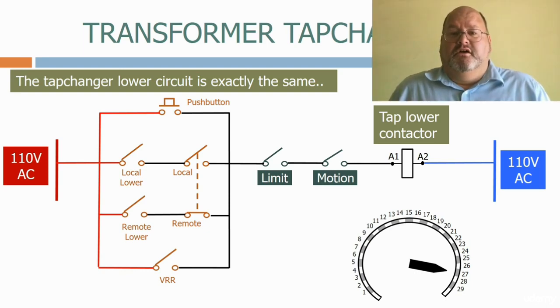In my experience, on-load tap changers are one of the main fire risks in high-voltage substations, and I have lost several expensive transformers over the years when they've failed. The main issue is the integrity of the moving contacts inside the on-load tap changer, which deteriorate over time, especially on networks where the voltages need to be continually adjusted to stay within the thresholds required. To try and prevent these failures, on-load tap changers are subject to extensive maintenance programs, which kick in once the transformer has completed a certain number of taps.